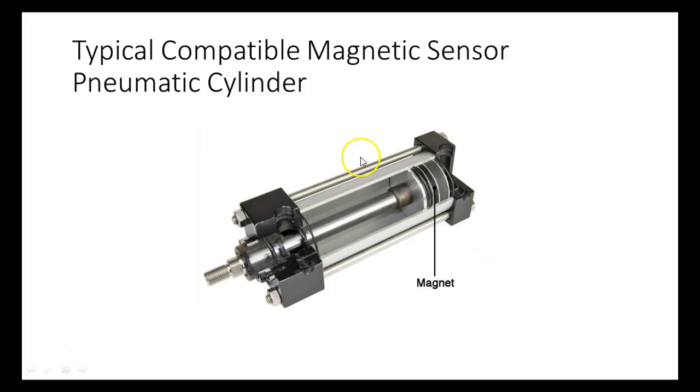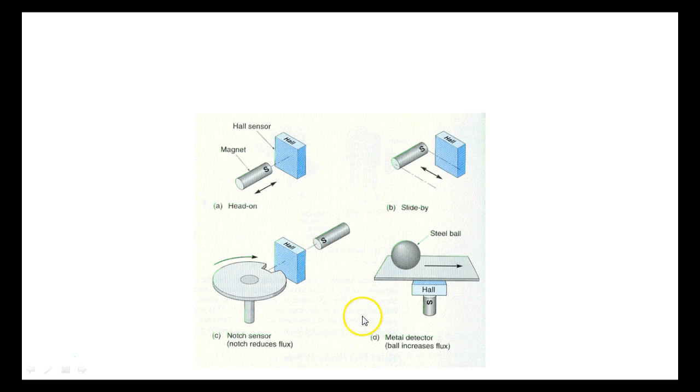This is a standard magnetic. This is a pneumatic cylinder that's specifically designed to run with either a Hall effect sensor or a magnetic reed sensor. In the piston, they got a what? They got a magnet. Or you got a burglar alarm in your house, and you've got sensors on your windows to keep people from opening. Well, the moving one is a magnet, and the one that mounts permanently, which has to be the electrical power, is a reed switch. That's what they use in burglar alarms. These things you put on your box.